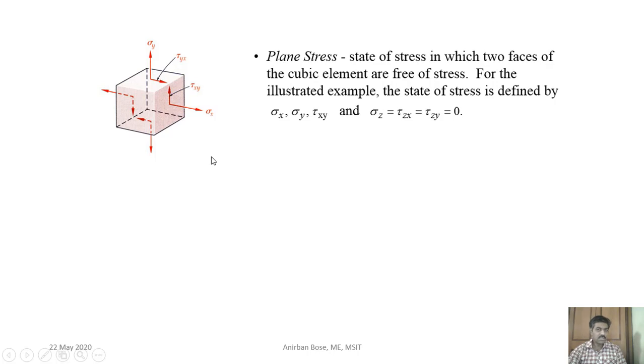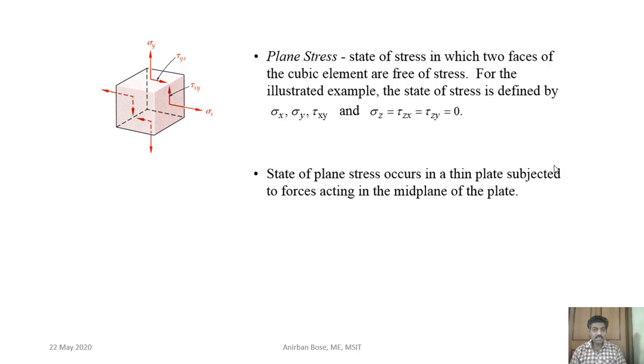This situation is called a plane stress situation, and it is not that plane stress situations are not found in practice. There are very many situations that we can consider as plane stress. It is not only for the simplification of the mathematics. Definitely it will help simplify the mathematics, but there are many practical situations where the plane stress assumption is good. For example, the plane stress assumption is true if you consider a very thin plate subjected to forces acting at the mid plane of the plate.